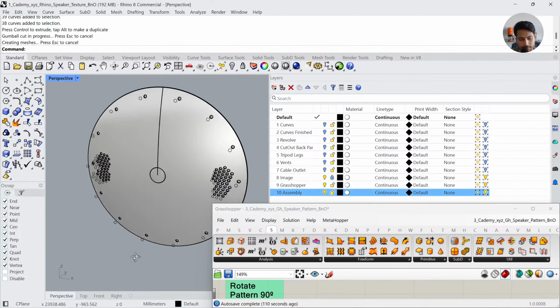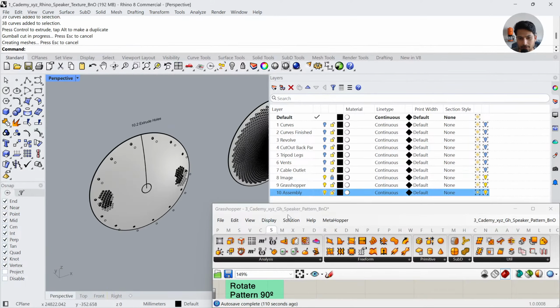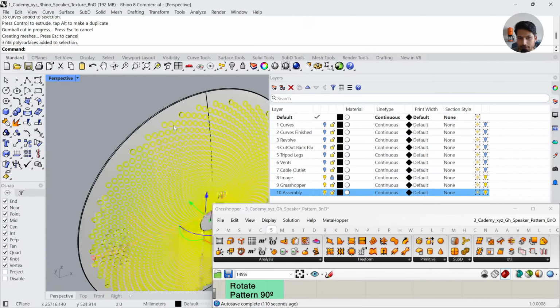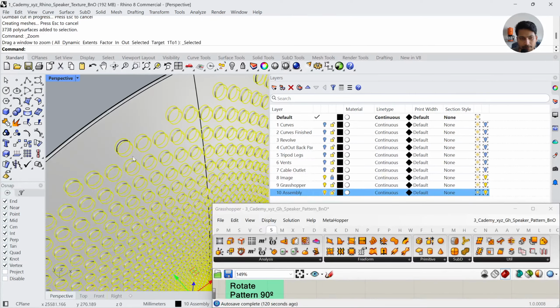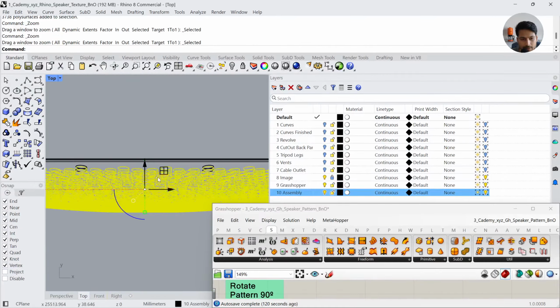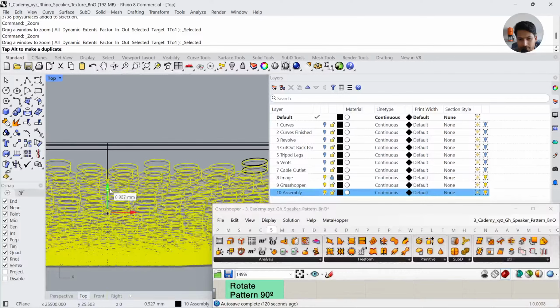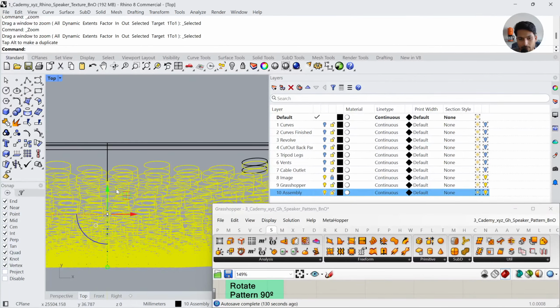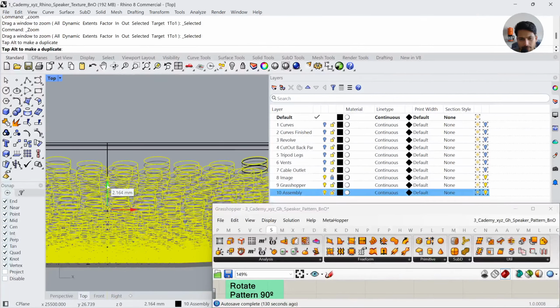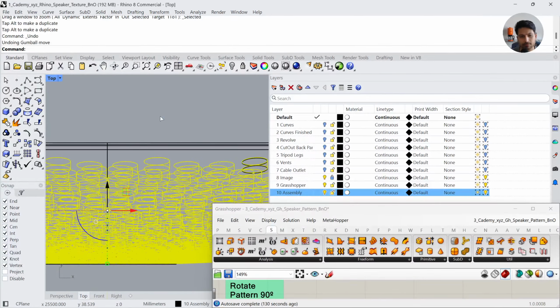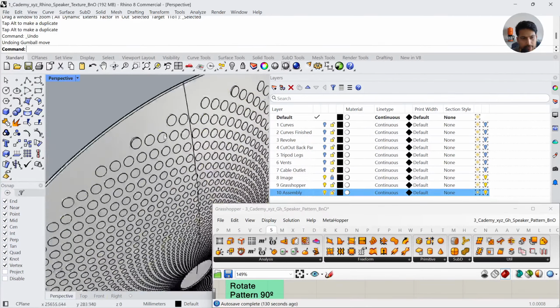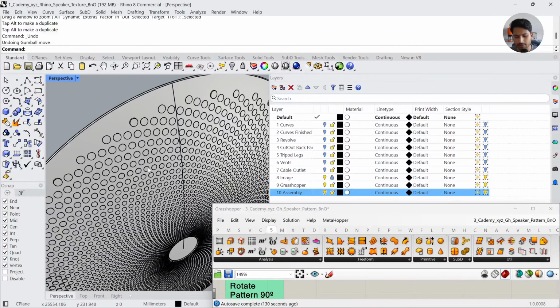Okay, so you can use the same line cut option. These are the intersected parts that I showed you earlier. And the only thing that I'm doing different here is that I'm moving the object to provide the thickness. I'm moving it by 1.5 units. Okay, and finally we can perform Boolean difference.